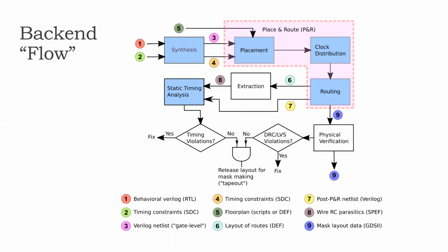Okay. So for example, what standard cell files will the placement tool need? Well, it will obviously need the LEF of the standard cells, because it needs to know the dimensions of each standard cell, where the pins are, and so on. It actually doesn't need to know where the pins are, but it needs to know what the dimensions of the standard cells are, what's the width of each cell, so it can place it correctly. So the placement tool will need to read the LEF. The placement tool also, because it has to be timing aware, needs some awareness of delays. It also needs to read the .lib.